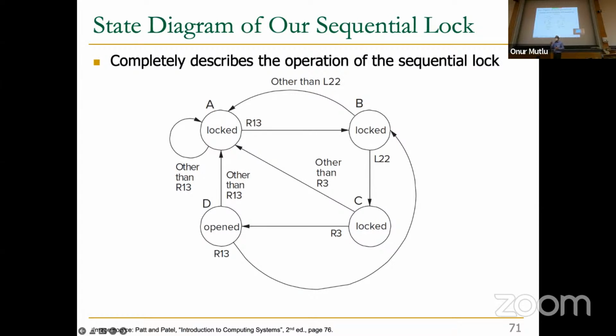Well, actually, there's something missing, which is a reset state. There should be a reset input, which goes to the locked state when you lock it, actually. But basically, where you start from is the key question, right? That's what's missing in the state diagram. You should never miss that out in a computer circuit. Here, it depends on what you have done with the lock, locked or unlocked, but we're not going to cover that.